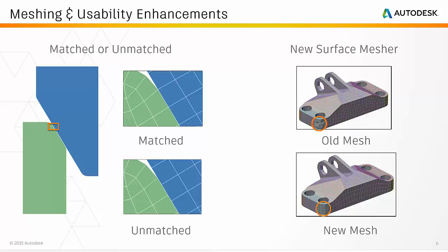In the 2017 release, a new option is provided in the 3D mesh settings for assemblies, and it's called Create Matched Mesh Between Parts. This option is enabled by default. However, unchecking this option increases the success rate for meshing assemblies. The Nastran solver, when available, is recommended if an unmatched mesh is created. Note that simulation mechanical solvers for linear, thermal, and electrostatic analyses rely on smart bonding if welded or bonded contact is used between parts with an unmatched mesh.